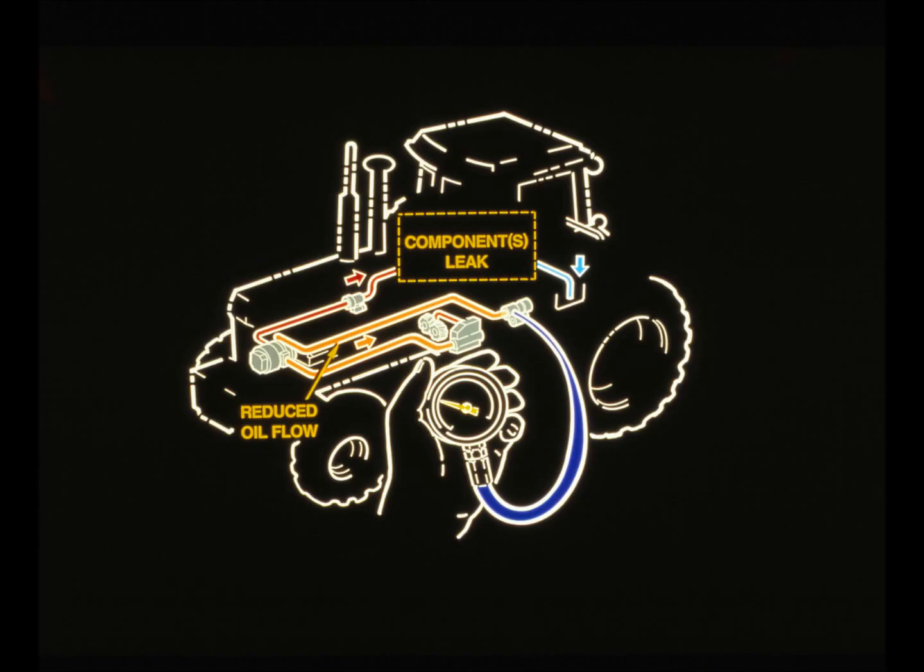Let's assume there is a substantial leak in one or more of these components: hydrocushion seat, brake valve, or differential lock valve. A leak that goes from high pressure to sump. The leak reduces oil flow to the return oil manifold. That reduces lube pressure.